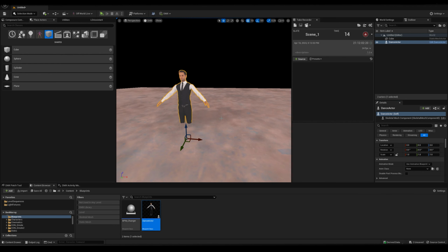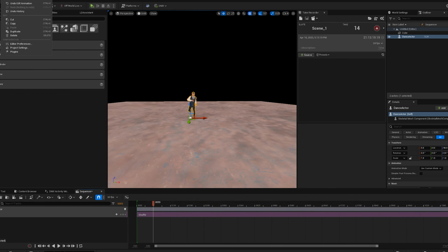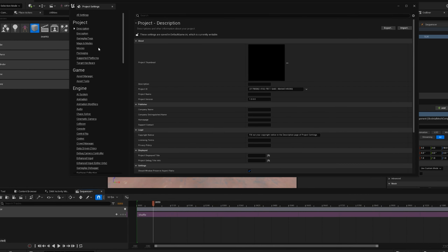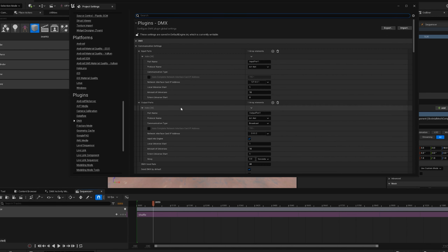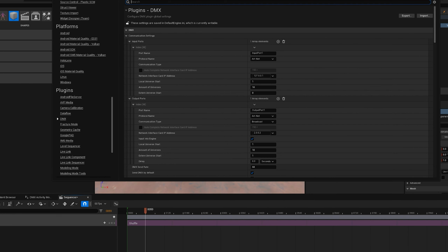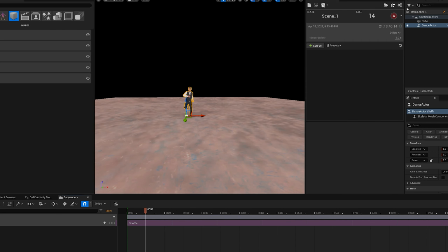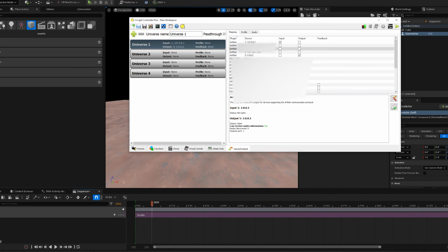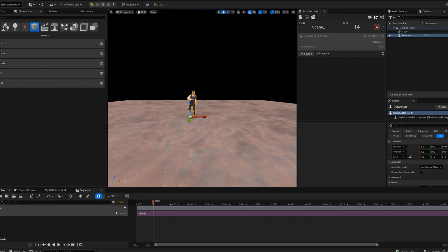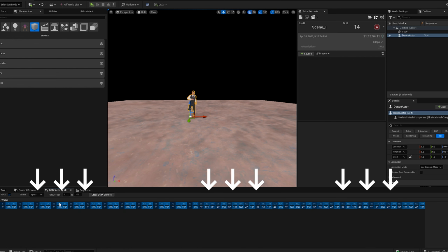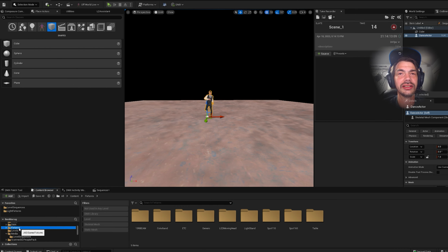Add that in. From quick settings, we'll jump into our DMX settings. I just use 127. In our local settings, I do use universe start of 0. For output, I have it at 2.0.2, but I don't think that it's necessary. We're not using output for anything. And for QLC, I have the same thing. So if you do those settings and have Soundswitch open, you should get some sort of reading. And if you're not, you probably should quit and never try again.